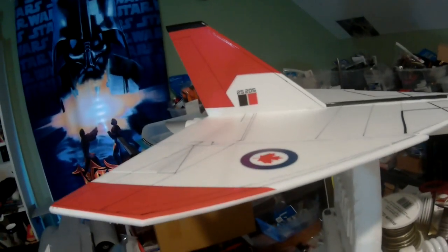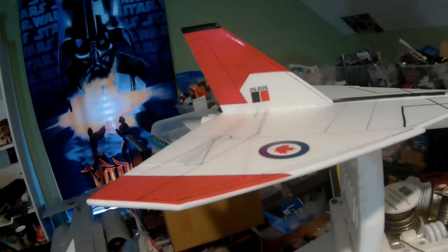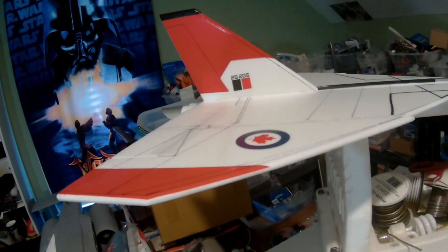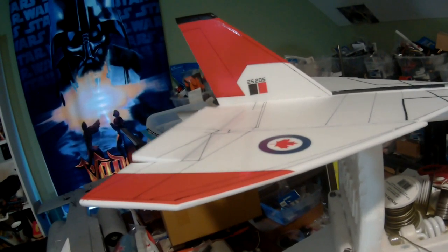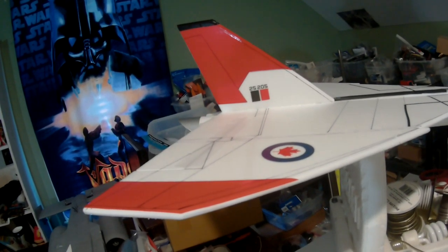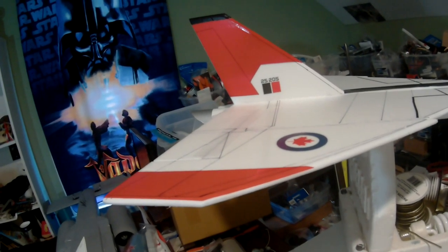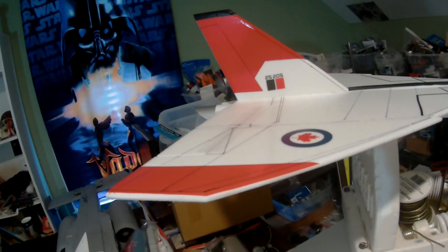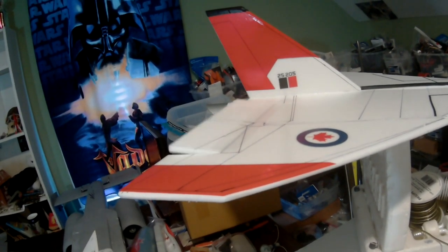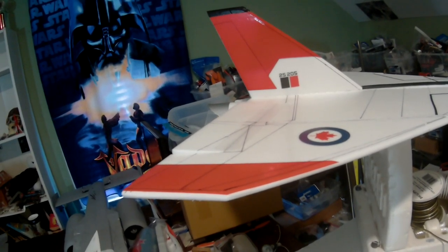so let me back out of this, and we can look at the plane. And with it in launch mode, the elevons are level. If I give a little bit of up, then you see they work, and they work as ailerons as well. When I want to transition to glide and landing mode, then I flip the switch. We get a little bit of up, and they continue to work as normal, just the offset is 16% up.